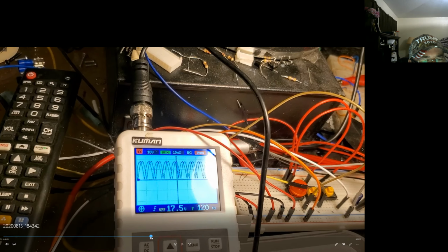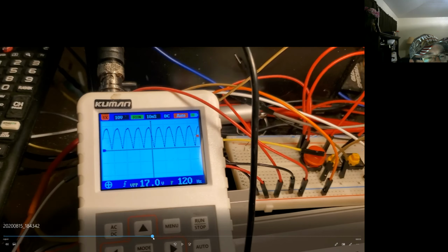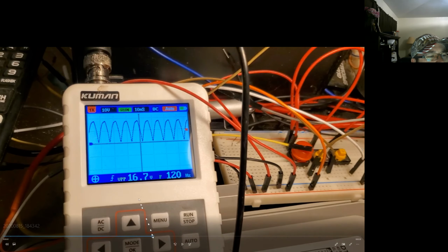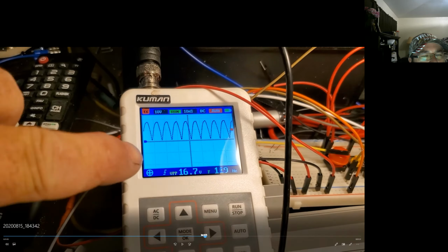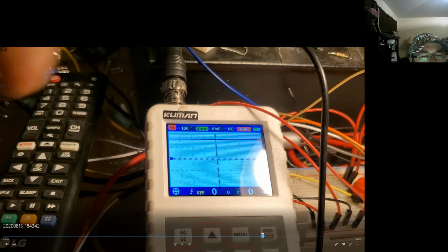Then you got your full wave like this, and you got your hump. So basically, when you send this to capacitors, this is all DC, your negative, your 0, and then your positive coming out. It's going to charge up the capacitors to the peaks, the tops, which you're going to see when I hook it up, and then you get this.